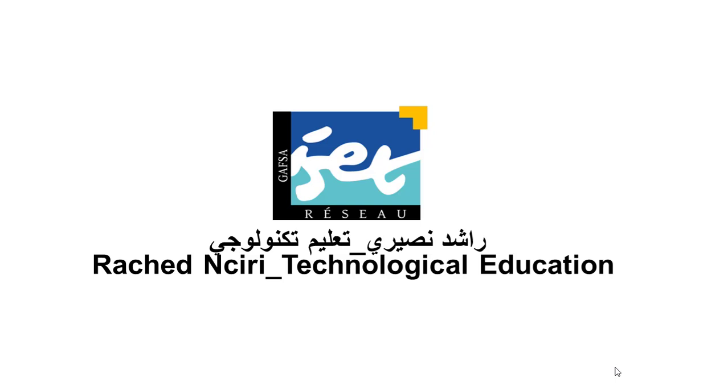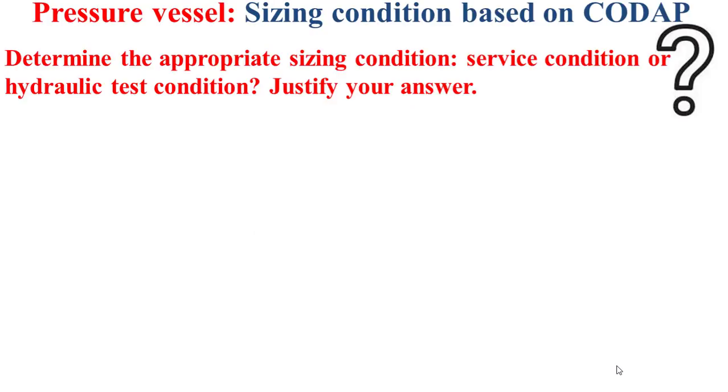Okay, let's go. Well, it's to note first that theoretically we have to determine the thickness of the shell or of the formed head of the pressure vessel under the service condition defined by its service pressure and service temperature, and also under the hydraulic test condition defined by its test pressure and test temperature. And finally, we have to take the greater thickness between the service condition and the hydraulic test condition.